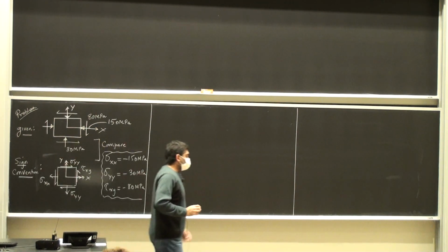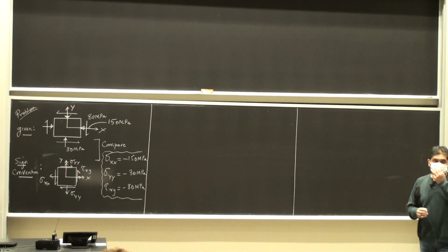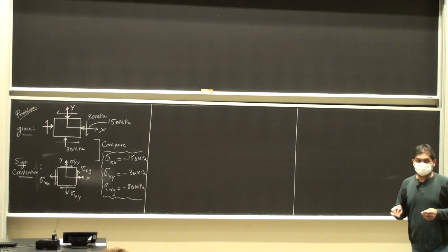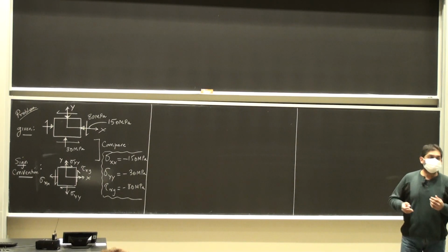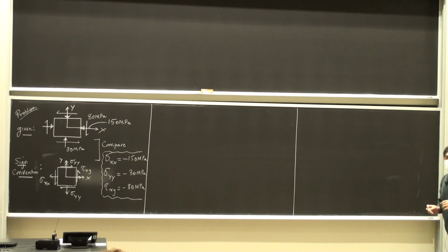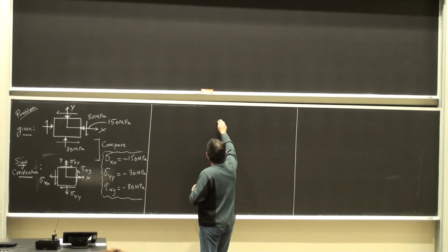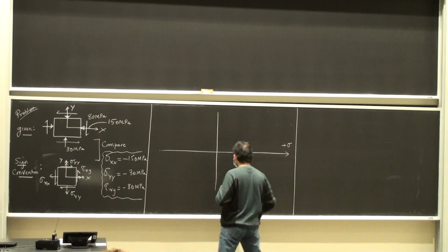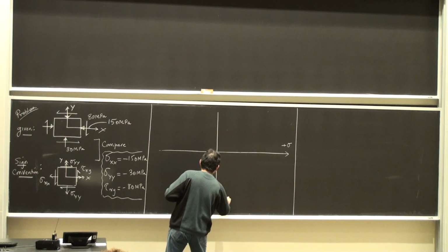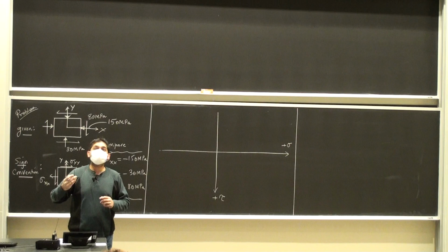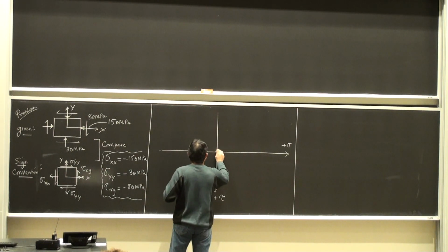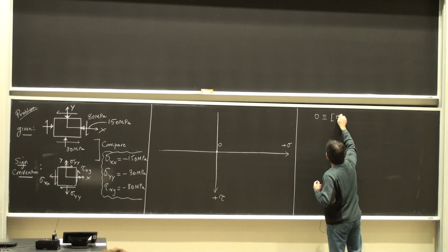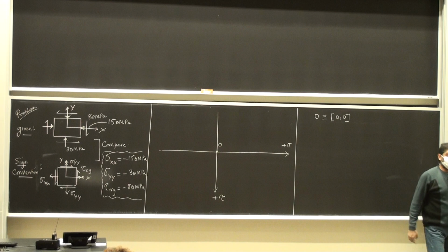Once we have this, then we start off to draw the Mohr circle. We set up the origin, we set up the center of the circle, which is not necessarily the origin of the coordinate frame, and then we have the radius. Okay? So first of all, the Mohr circle axes: positive sigma, positive tau. The origin is O, 0 and 0 megapascals.